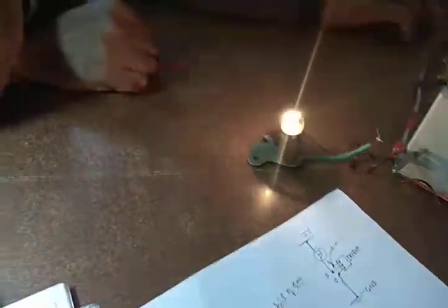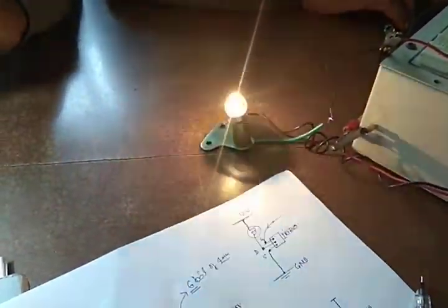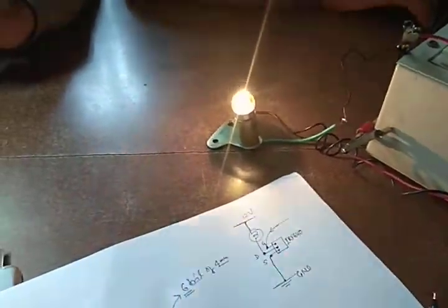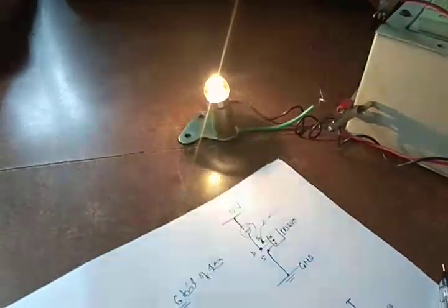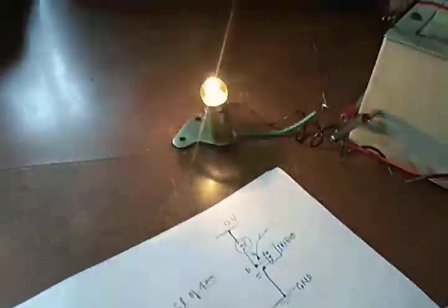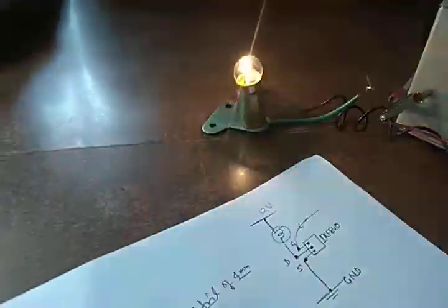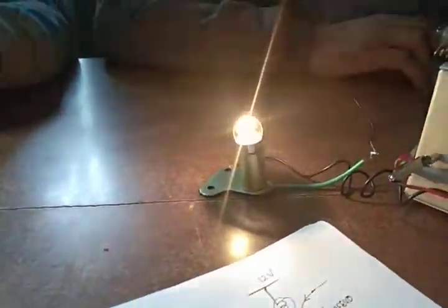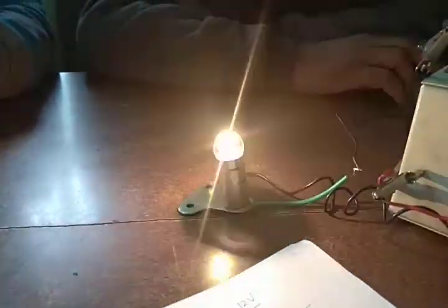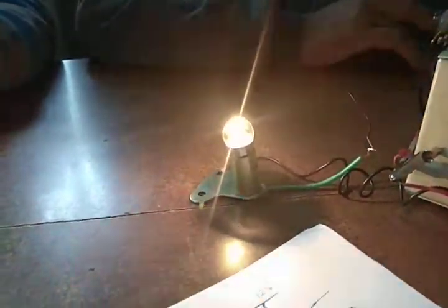for testing purposes, because if we set the frequency at 10 kilohertz, it is difficult to visualize the result of the required frequency, whether it is correct or not. At 10 Hertz it is possible to see by the naked eye the on and off process of the MOSFET, so we set the 10 Hertz frequency for experiment purposes, but in our project we set the frequency at 10 kilohertz.